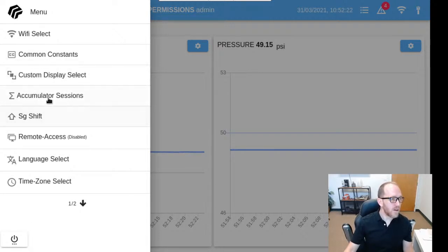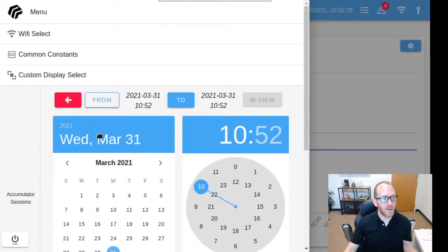That's a fun one. Accumulator session. So there's an accumulator screen. If maybe you're dredging, or you're getting paid for micro tunneling, and you're removing solids and you're getting paid by how much you're removing, you can start the accumulator. It will start basically a counter of how much solids you're removing based on what you put in for your solid component density and your carrier fluid density.